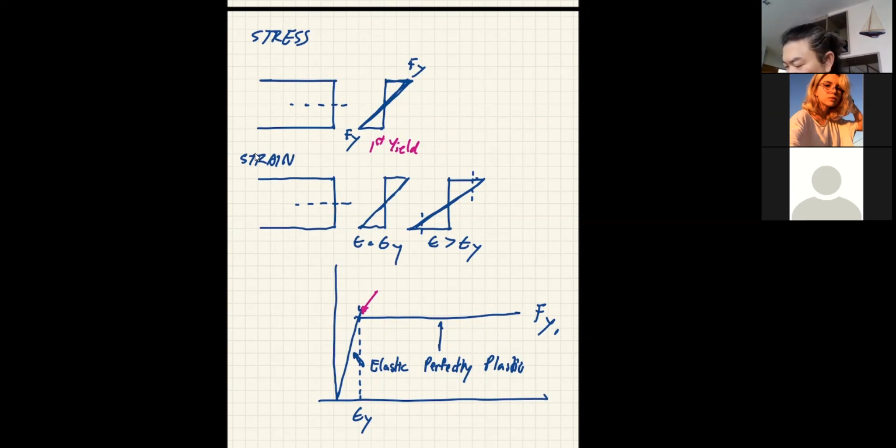Remember that the stress will remain flat like this, right? It could not go beyond the Fy, but right here, it will reach the Fy as well. So the yielding will creep in. Now your section begins to yield more than just the outermost fiber.